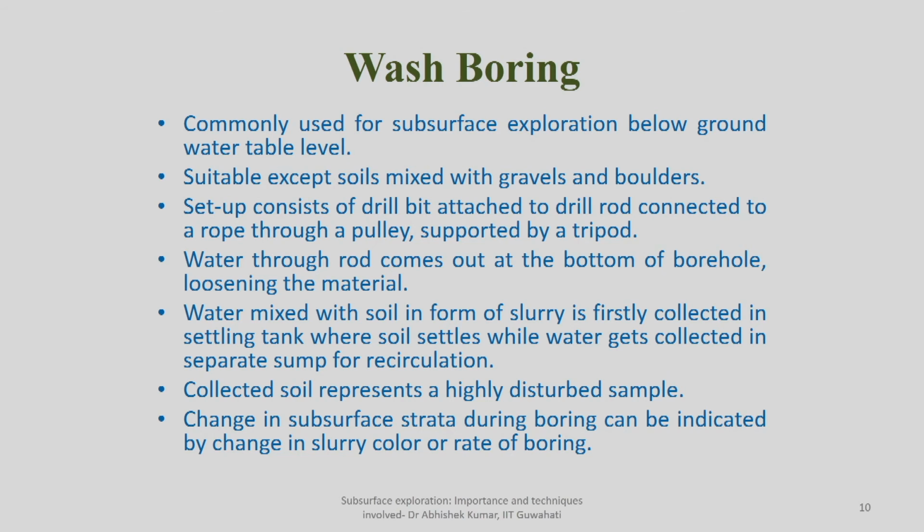So as the name suggests, because the soil which was available at that particular depth is now mixed with the water, this soil is highly disturbed. That's what is written in the second last point. The collected soil samples are highly disturbed soil samples. But as I mentioned earlier, borings are particularly used for advancing the borehole, so that you can very precisely and quickly reach deeper depth and then collect the soil sample.